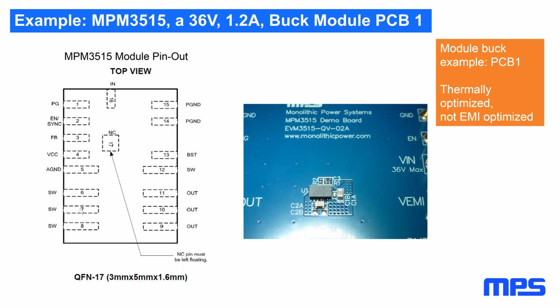On the left side, I have the pin out, and you can see we have the output pins, and there are also switch pins. Normally, you don't need the switch pins on a module. However, the module is constructed, as you have seen, with the inductor inside here, and in this area the IC is inside. And that has some bearing if you want to make a very low IQ design.